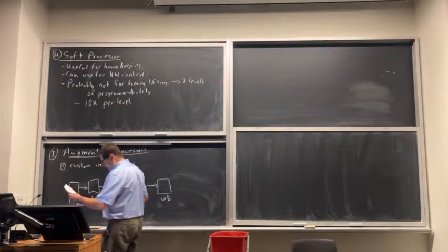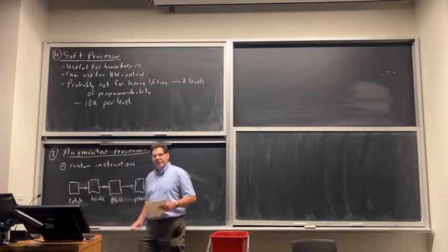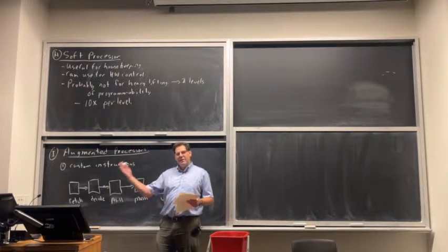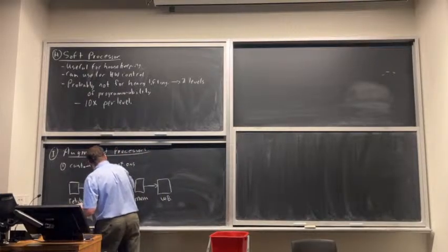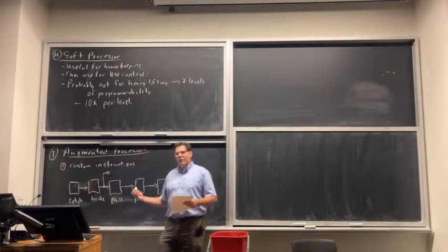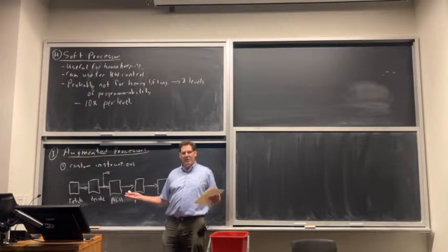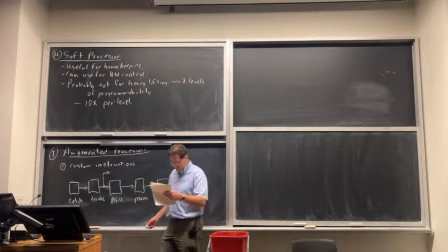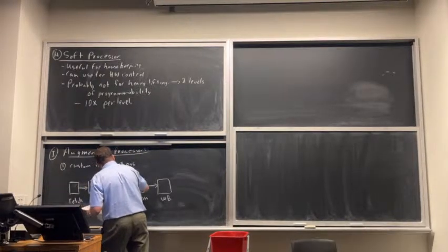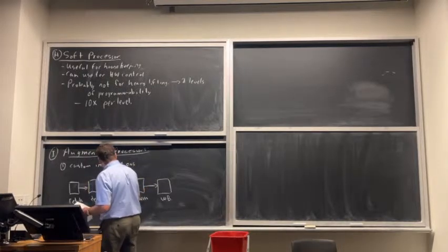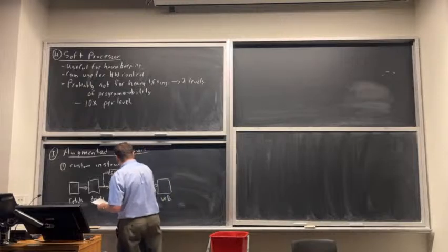So what a custom instruction does is, right after decode, where I've figured out what the instruction means and read the operands from the register file, I can say if it's a certain reserved opcode, you make some opcodes that the processor doesn't do anything with. They have no meaning to the basic processor, and you can use those opcodes. When one of those opcodes is detected, it just broadcasts it to some custom hardware that you wrote.